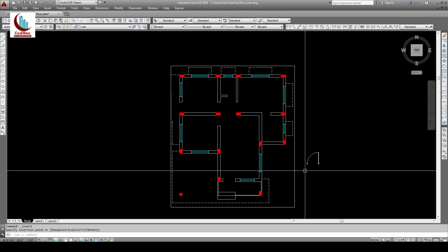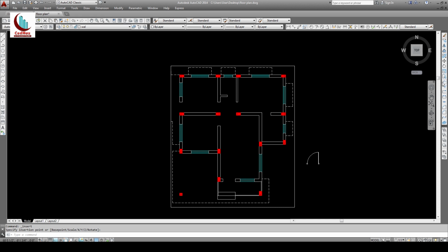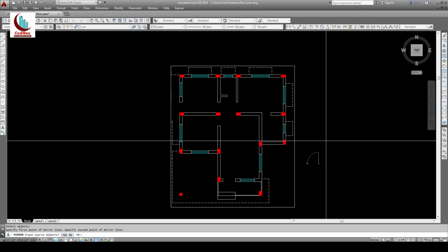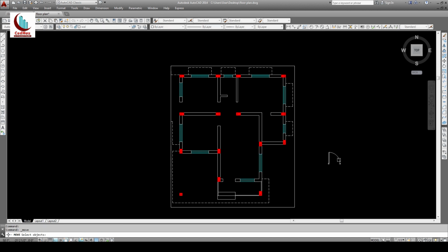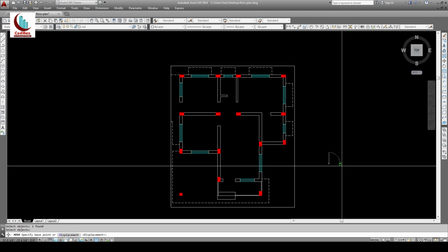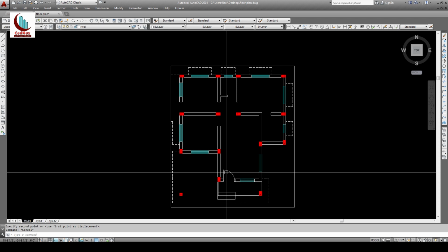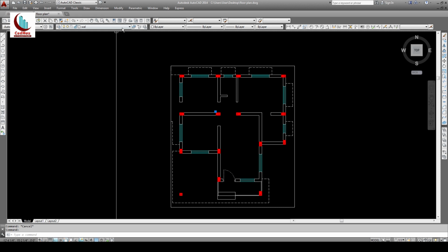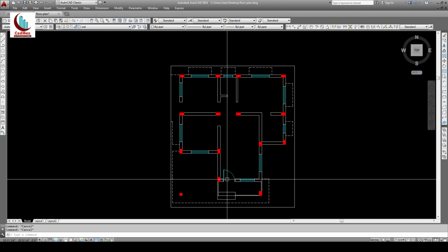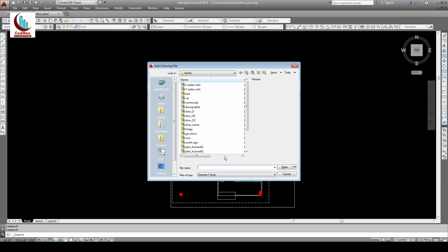Place the door here. Okay, but the door has to be mirrored, not like this. You can go to select mirror, enter, mirror is like this. Okay, here is this, move this, select this as a base point, second point here. Okay, now this one also you can put inside the window layer. So select this and go to layers, window. Okay, done.